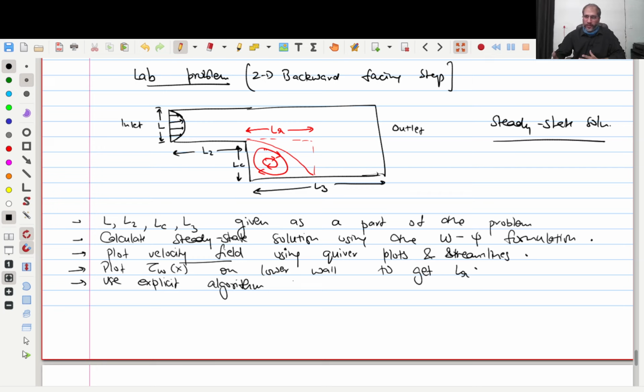That is irrelevant. You start with any omega value, and don't take it as a very large number, but you start with any omega and psi value. Psi is calculated from omega, so in fact you can start with any u and v values, and then you will see that the steady state solution will not be dependent on the initial condition, because that's by definition the situation where it stops changing with time. So that del omega by del t term vanishes altogether. The steady state solution should never be a function of time, because the time term is not even there in the equation.